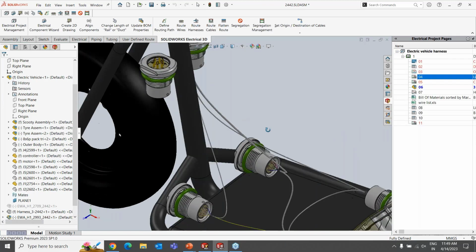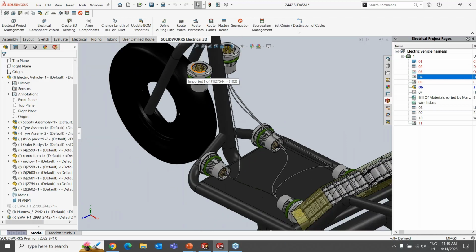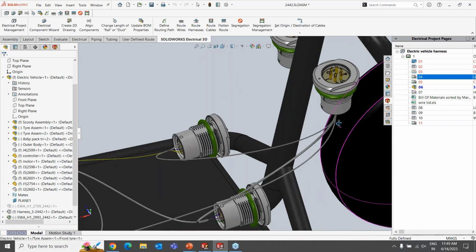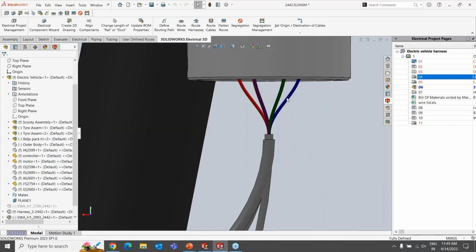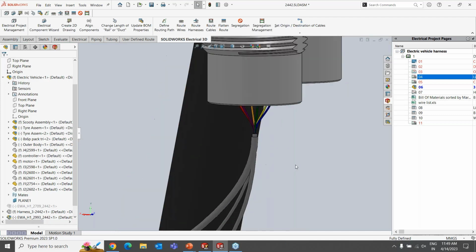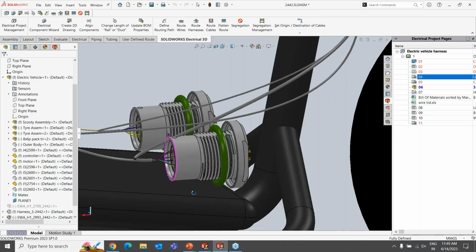So right now I have disassociated the first J1 component. I've only selected the other components. That's why you can see only the wiring available for this. And you can also see the branching between the harness in such a way that all the other colored wires are also shown, the core wires that are being used. Similarly with others as well.